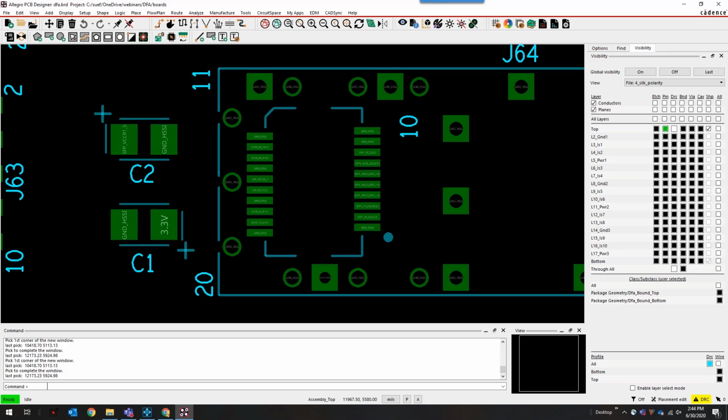Okay, great. So another question we have is, how do I get to the distributor search? So that's through CIP in the schematic. So that allows you to interface with your database as well as go out to your distributors and to Silicon Expert if you want to do that. But you do need to use CIP inside of Capture.